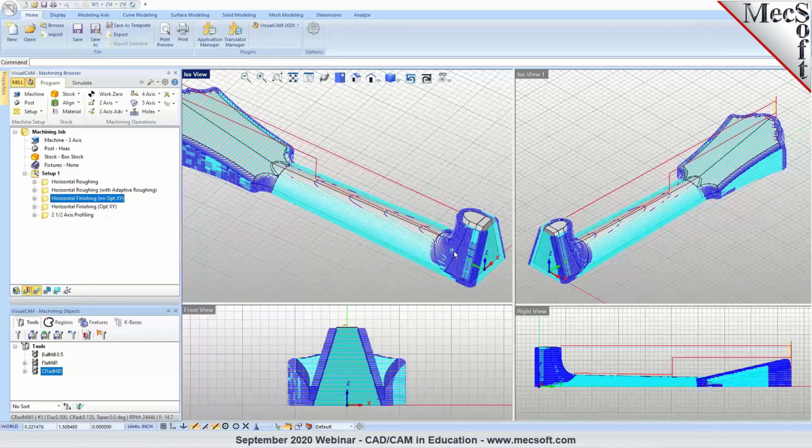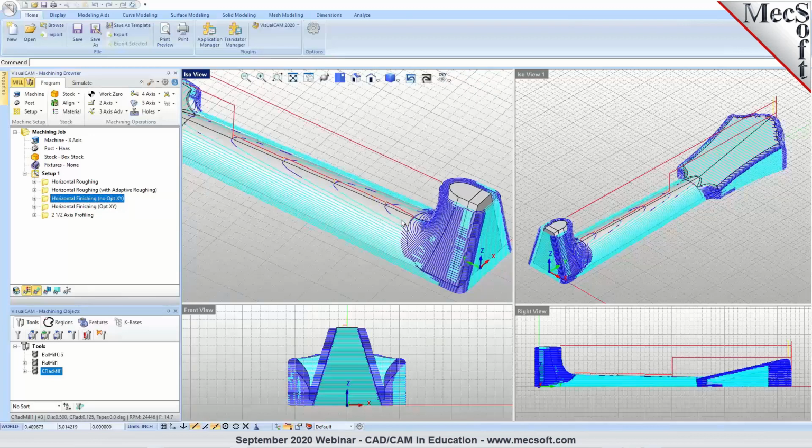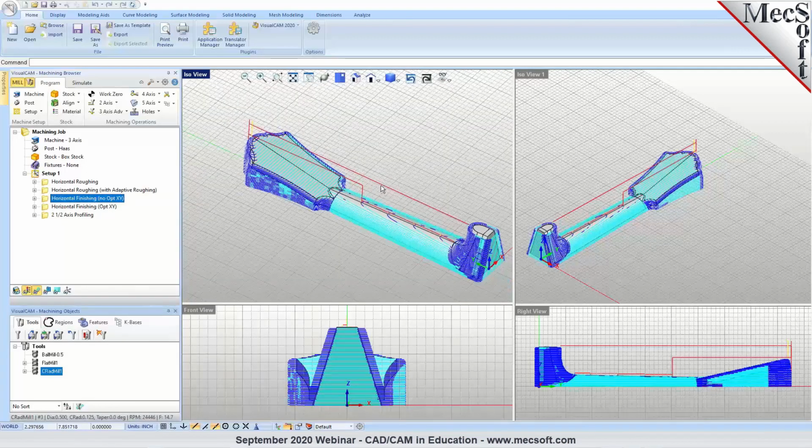And what you see here is that as the XY Z-level planes are sliced in order to calculate the toolpath, in the area that's near flat or just barely radiused on the neck, you see the widening between the toolpaths, and that's going to leave cusping along the neck, and it's going to leave a lot of cusping along here, which you would normally have to go through with another operation to clean up.